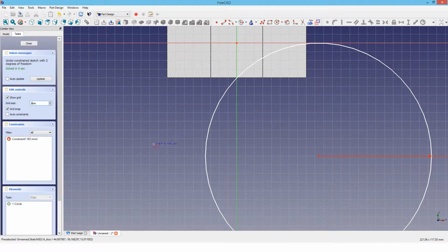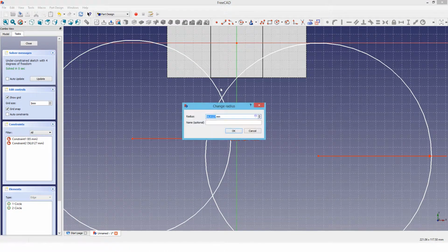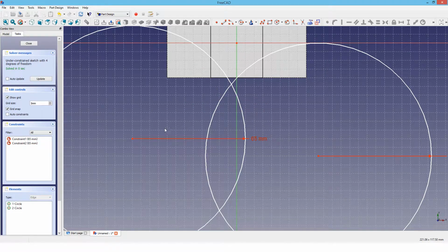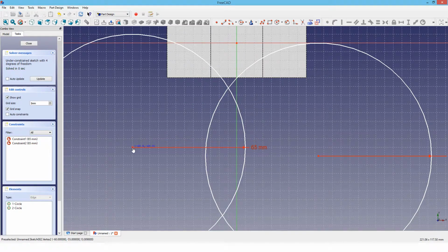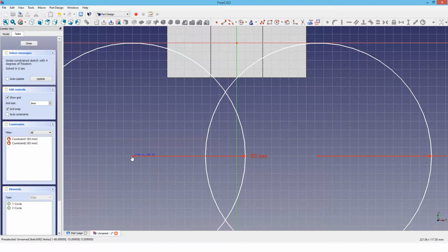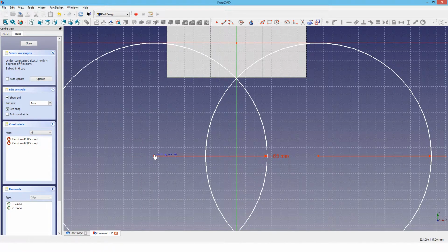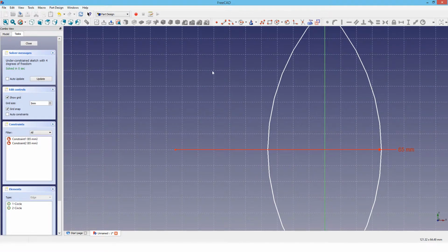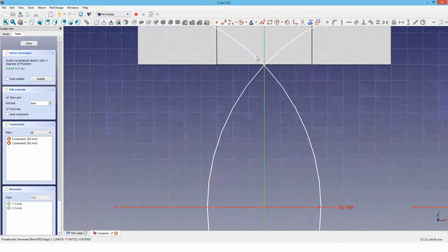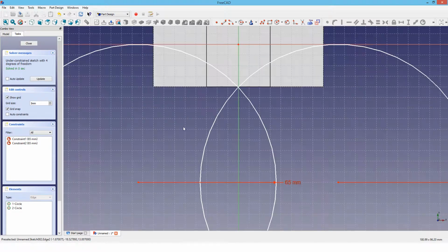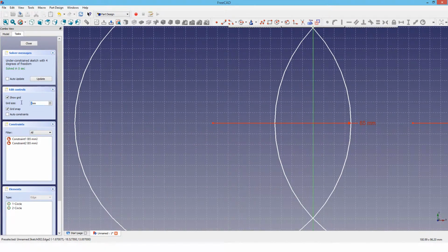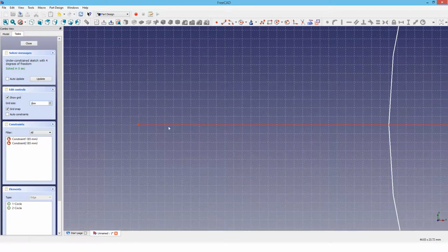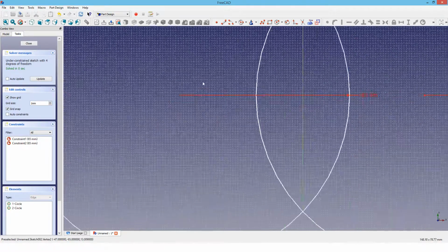And we'll create it here, and we'll give it a constraint of 65 millimeters, and then we're going to move it to the same height and roughly the same position, and then we'll move it with 1 millimeter forward should be okay. There we go.